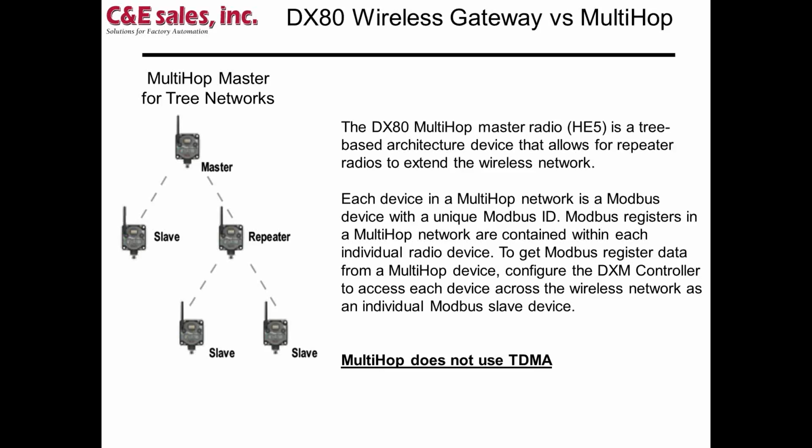Traditionally in this mode, you have to have some type of master device, PLC, HMI, controlling this communications. So one added benefit of the DXM100, it can be that master, so you don't have to have that external device. It can do this reading and scheduling of reading. Because this doesn't follow TDMA, devices can talk on top of each other if it's not managed correctly.